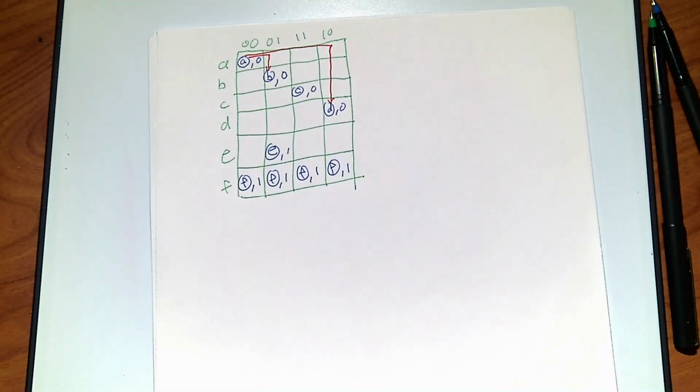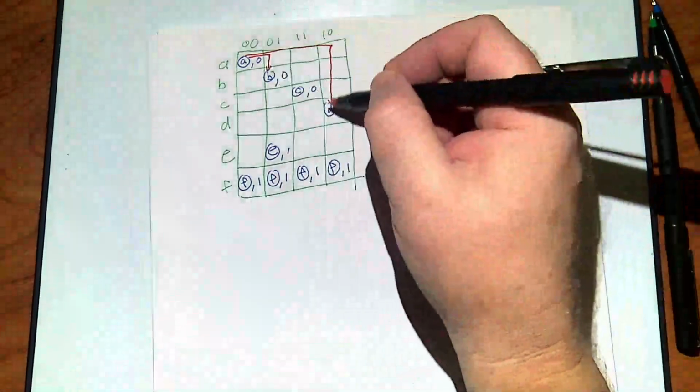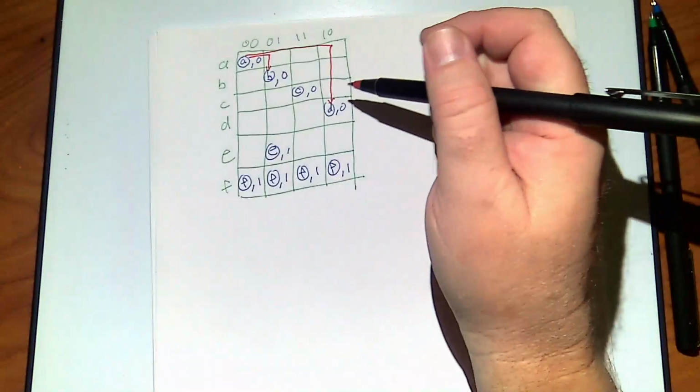So if I'm in A, one way to leave that state is a 0, 1, and another way to leave that state is a 1, 0. But I'm not specifying anything for 1, 1, because now you have to do a race condition, and I don't know what's going to happen. So I'm just saying I don't even want to deal with it. These are the only two functionalities I'm going to worry about.